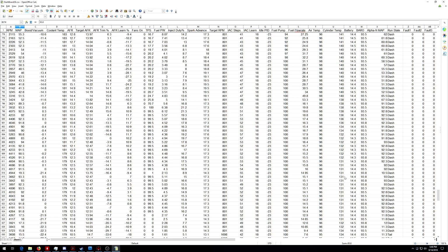So there's a few things that just from this table alone that has shown me. So one, obviously I'm getting a hesitation off of throttle, and this is a common problem. If you are stabbing the throttle and it's hesitating or it's bogging, what is often happening is you are getting a lean condition, and the EFI is dumping a whole bunch of fuel, causing a rich bog condition.